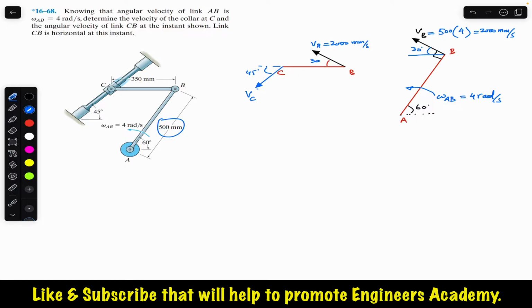Now we are required to find the angular velocity of link BC. If we see that initially the mechanism is like this, then after some time t, this point B will move up and this point C will move downward. So we will have link BC in this orientation, like after some time t. As we can see, on this link BC, point B is moving up and point C is moving downwards. So overall link BC has angular velocity in the counterclockwise direction, and we are required to find this angular velocity, which is unknown.